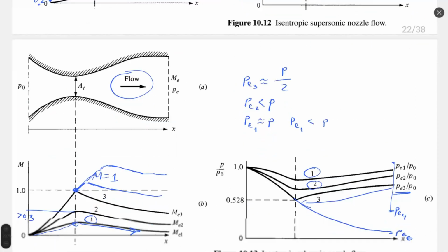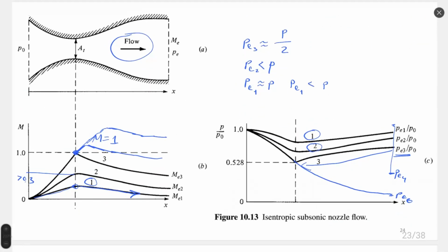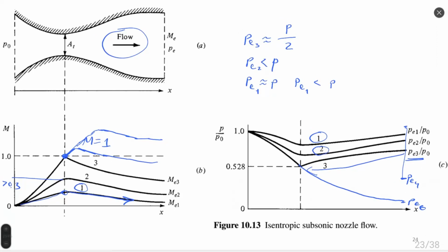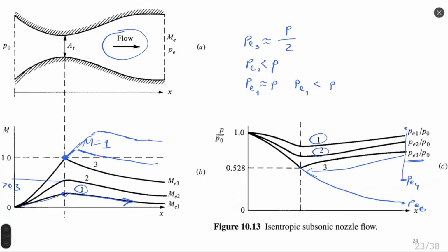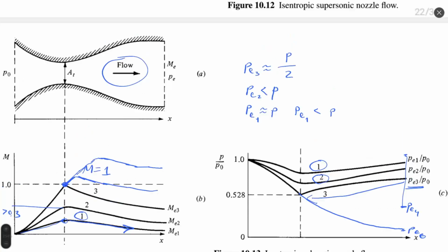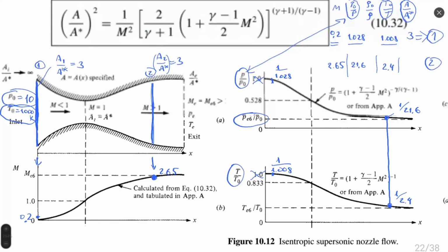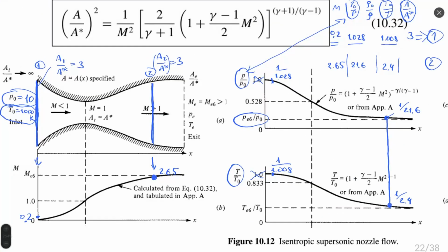So all is about pressure gradient. We need to see which is the pressure gradient, which is the pressure difference. Different cases can correspond to different flow pictures inside the nozzle. The case we had here in isentropic flow corresponds just to a case when energy is enough for continuous acceleration.